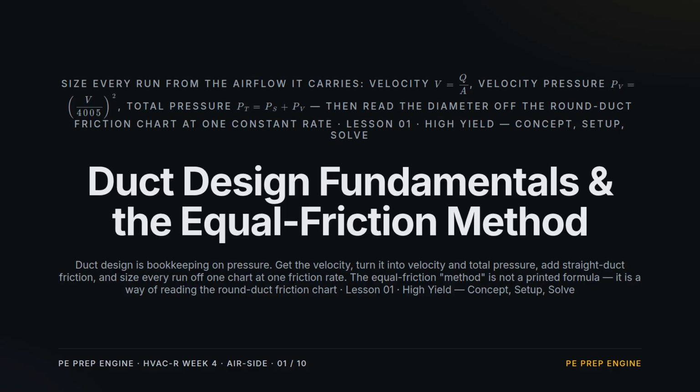Week 4, Lesson 1, Duct Design Fundamentals and the Equal Friction Method. Duct design is bookkeeping on pressure. You get the velocity, turn it into velocity pressure and total pressure. Add the straight duct friction, and size every run off one chart held at one friction rate.